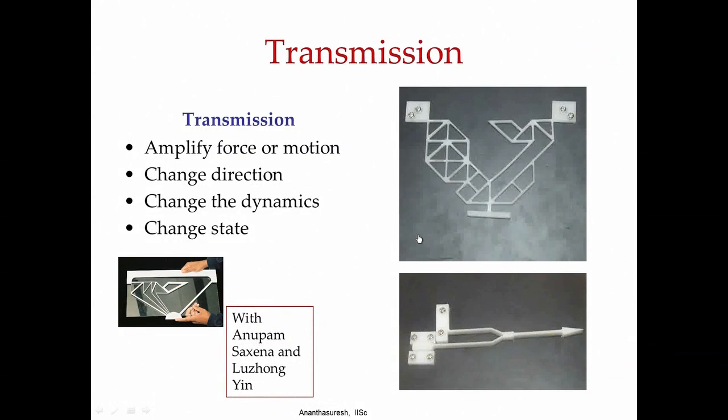There are other things where you can amplify displacement if you want. So, here is one that amplifies displacement. Let us look at the screen first. There are these movies of real prototypes where you are applying a force. It is just a big aluminum arrow that we have made to illustrate. So, you apply a force here, it is moving with a large displacement over there. This is a displacement amplifying compliant mechanism.